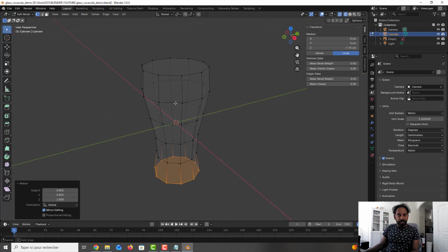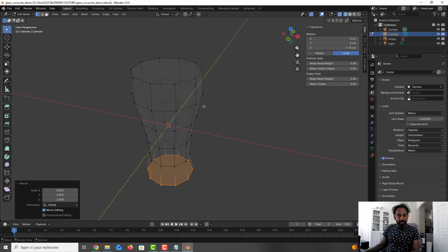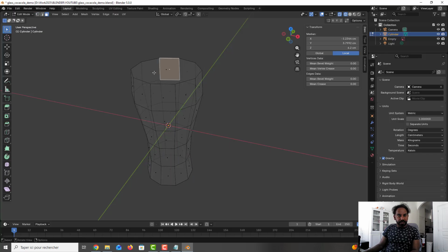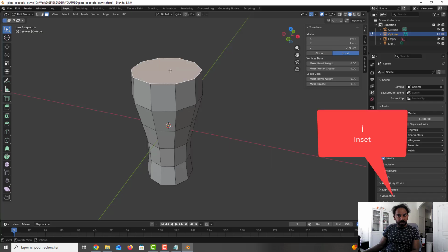Now we can check in the perspective view, and it's nice here. Okay. I select the top face. The easiest way is to toggle the X-ray mode. I go here. I press E, and it will be really small. You see?